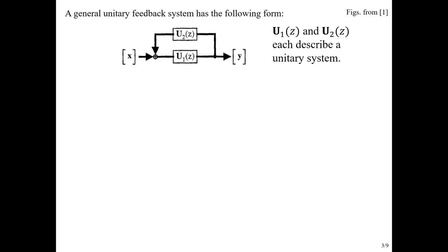And so then we can think of a matrix or multi-channel system. This vector is added to this vector and goes through this multi-channel transfer function. Typically the same number of inputs and outputs, although I suppose it doesn't necessarily have to be that in general, but for a unitary feedback system, it does. And then this part, in addition to being the output vector, goes into here, again a multi-channel transfer function that tells how that gets mapped to the signal that becomes the feedback signal.